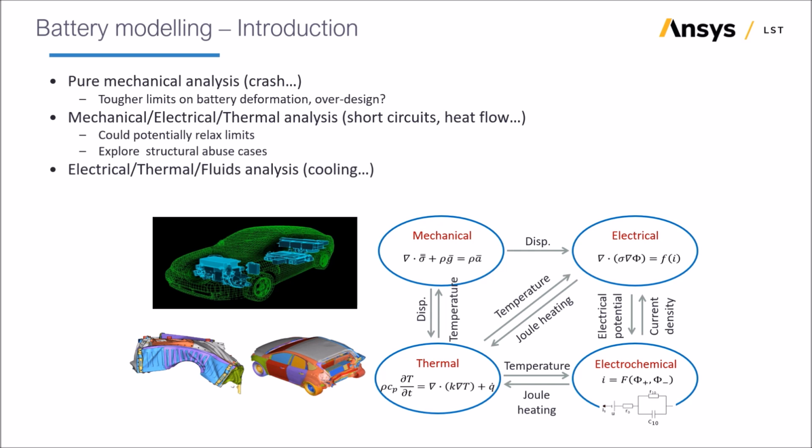One approach is simply to put a big protective structure around the battery and design for no deformation whatsoever. And for that, you need only the regular mechanical analysis techniques, but the structure might be over-designed. If instead you model the multi-physics effects that can lead to fires, it may be possible to relax the criteria somewhat. For this type of analysis, you need LS-DYNA's electrical and thermal analysis coupled with mechanical.